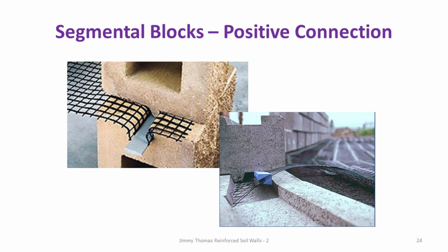For this to work, first the transverse ribs should take the load, then transfer to the longitudinal strip, which is possible only if the junctions are strong. In this case, the junctions are very poor. It is only the PVC coating which holds the junction. So if you try to put this type of connection, it will not work.